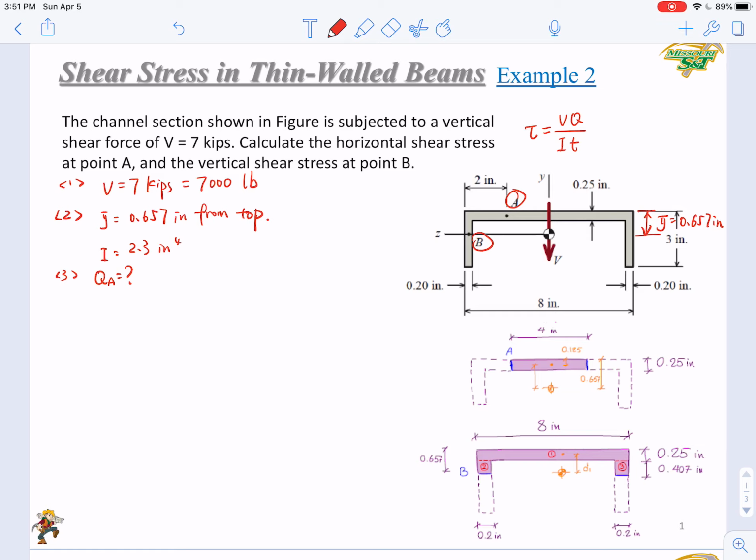As illustrated in the previous slide, for this kind of C-shaped cross section, if we're calculating the stress at this point A, then we'll cut this area from here to a symmetric point on the other side of the centroid. Not half of it, not cut from the point to the y-axis. We need to cut it to the symmetric point on the other side of the y-axis. You get such area.